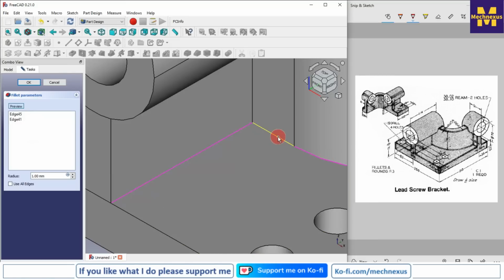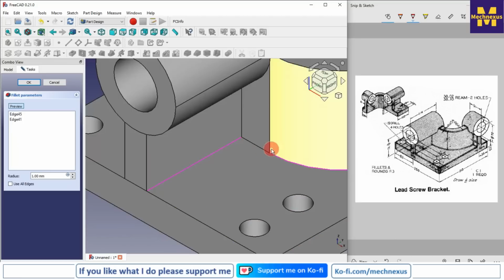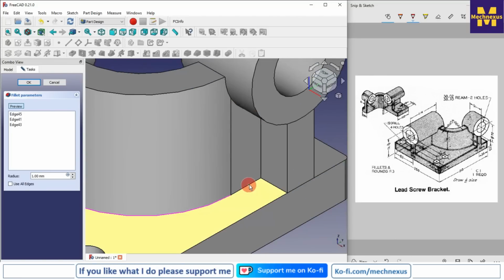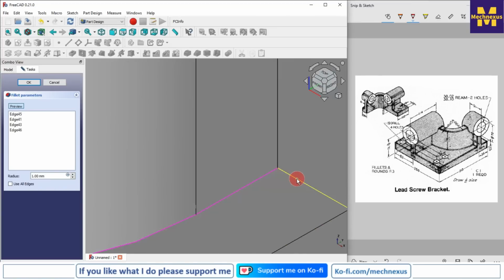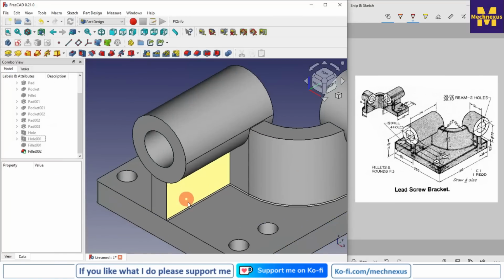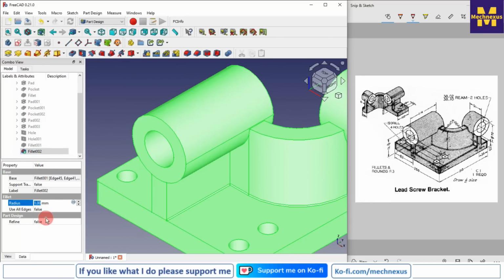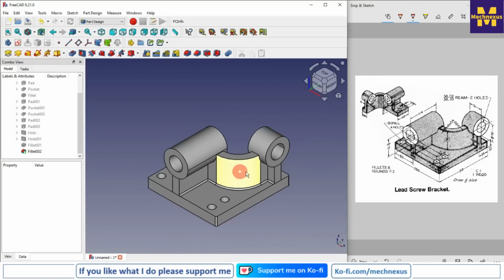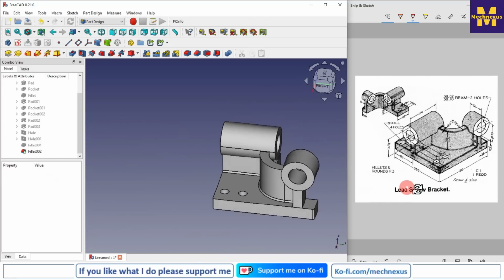Select the edges, zoom in, and click on OK. So you can see that we have added the fillet. So the radius is R3, update it. So this is how you can add the fillet at all edges available.